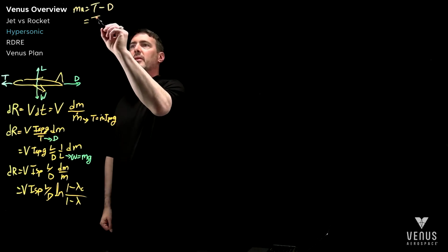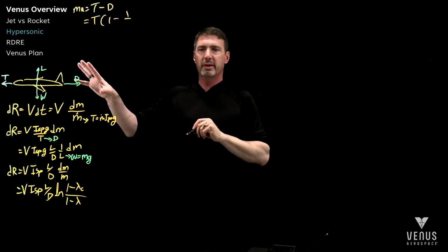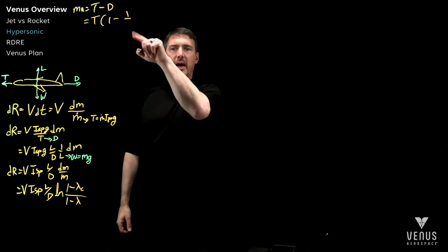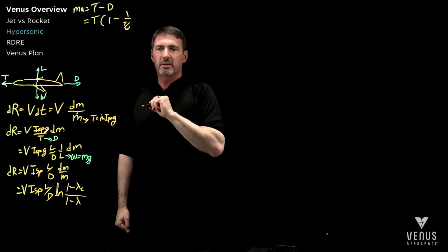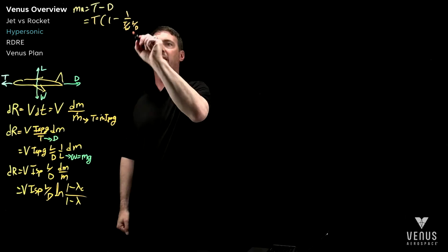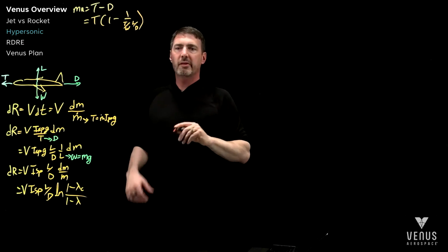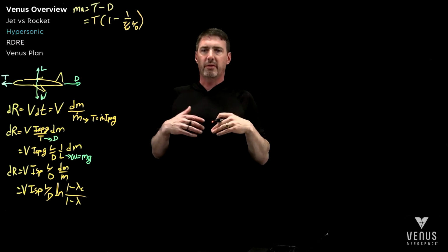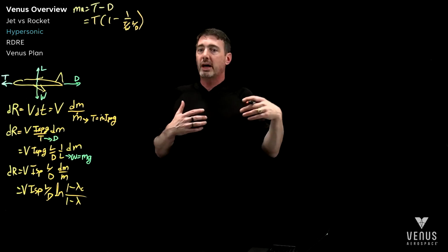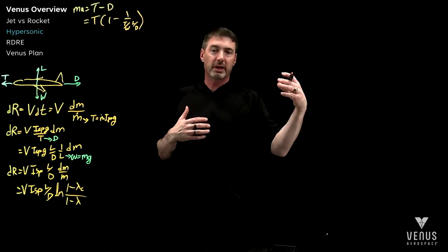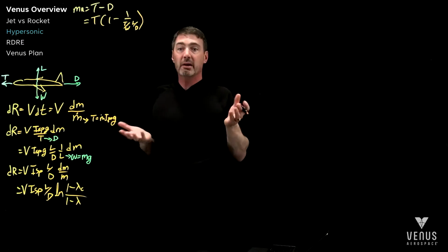And this is thrust 1 minus, and then we'll do the same trick we were doing here with these 4 vectors. And so after you go through it, this is thrust to weight of the vehicle, lift to drag. Right? And so this is important because if the thrust to weight of your vehicle is not very big, it'll take you a long time to get up to speed. You're fighting drag the whole time you're getting up to speed. And so there's a penalty. And so this term carries forth.